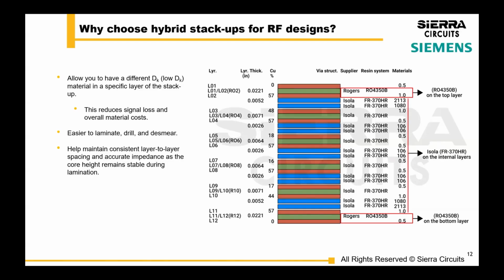Now, when you have hybrid stack-ups, there does come into play scaling, meaning one material like a Rogers will stretch and skew differently from an FR4. So the fabricator is going to probably have to run a first article as boards get more and more complex that are being made in the US, for RF, military, aero, those type of industries. There's really no clear scaling data that a fabricator has already built that job or something similar to reference.